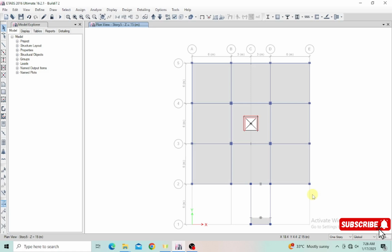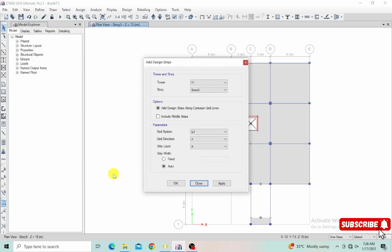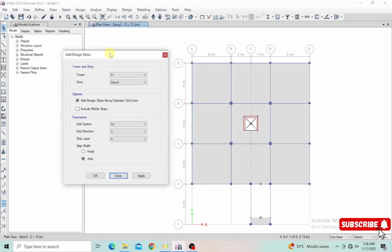Okay, so for us to start, we have to draw our strips. So we are going to go to Edit, and we are going to add or edit strip, and you add design strips. So once this box opens up, we are supposed to fill these boxes and everything. So the tower is T1, and the story, we are at story 5, and this is story 5. So based on the story you want to apply your strips at, you just select that story, and the strips you assign story by story. You can't assign it all together, so you assign it story by story.